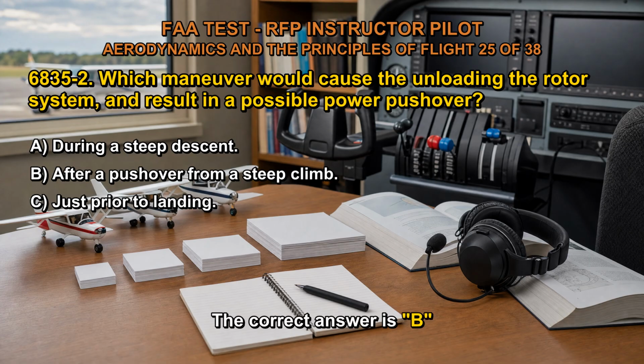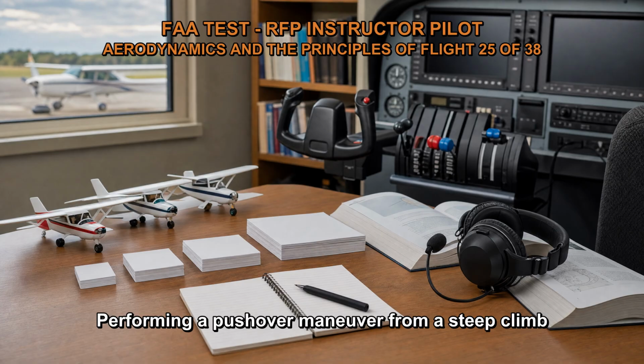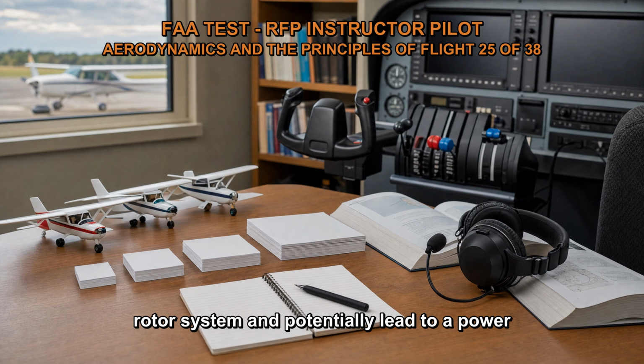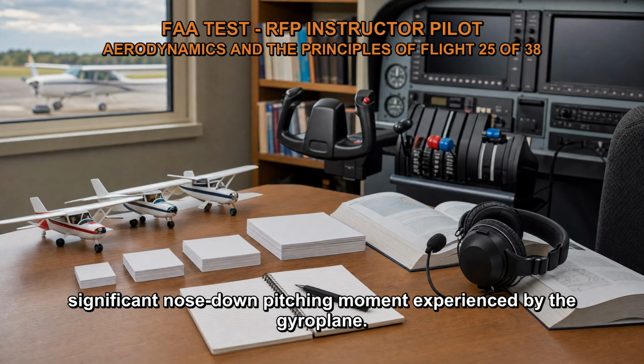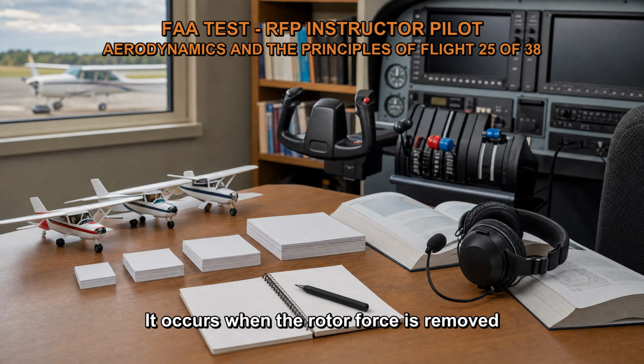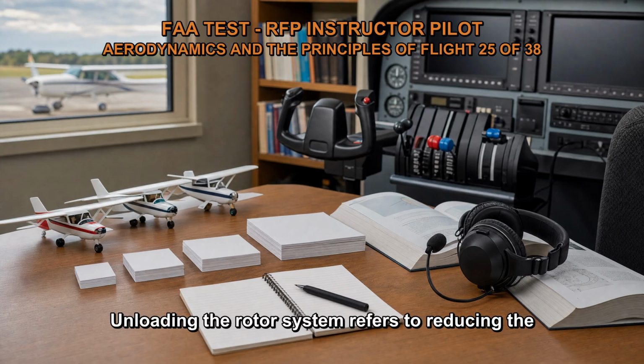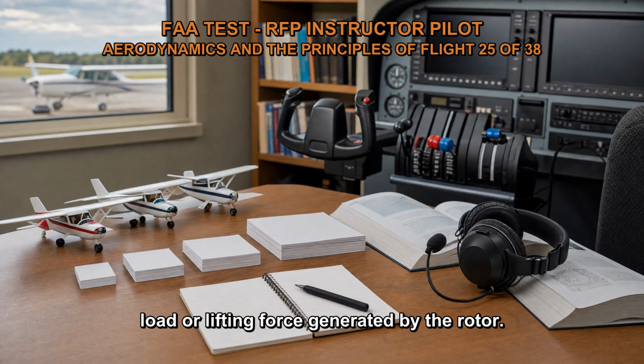The correct answer is B. Performing a pushover maneuver from a steep climb in a gyroplane can result in unloading the rotor system and potentially lead to a power pushover. A power pushover refers to a sudden and significant nose-down pitching moment experienced by the gyroplane. It occurs when the rotor force is removed or significantly reduced, causing the aircraft to pitch downward. Unloading the rotor system refers to reducing the load or lifting force generated by the rotor.